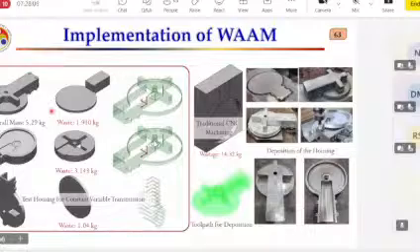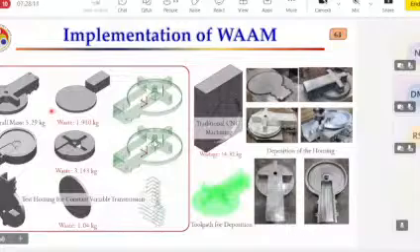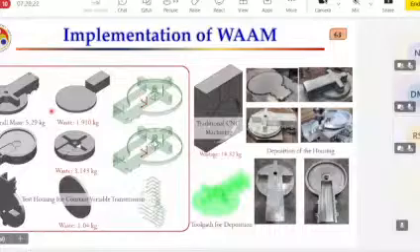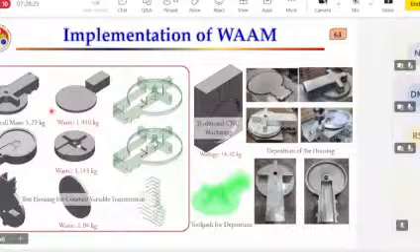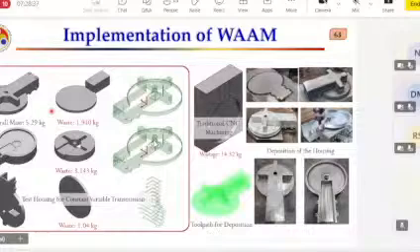The novelty over here is that it's Inconel. Inconel has very low conductivity, hence it stores the heat, because of which material drips at the end. So to avoid that, we have come up with a new tool path. As you can see over here, it's a discontinuous tool path where we transfer material drop by drop, and in this manner we're making this kind of structure. And you can see we have compared the cloud data also. So we have excess material over the required one, and you can directly machine it if you require a better surface finish.